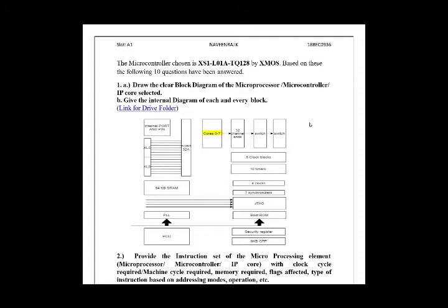Now let's talk about ports and clock blocks. Ports provide an interface between the logical cores and the I/O pins, input/output pins. Signals in different directions cannot be mapped onto the same port, so all pins of a port provide either input or output. The operation of each port is synchronized to a clock block. There are totally 6 clock blocks, and the ports' operations are synchronized with these clock blocks. A clock block can be connected to an external clock input, or it can be run from a divided reference clock.